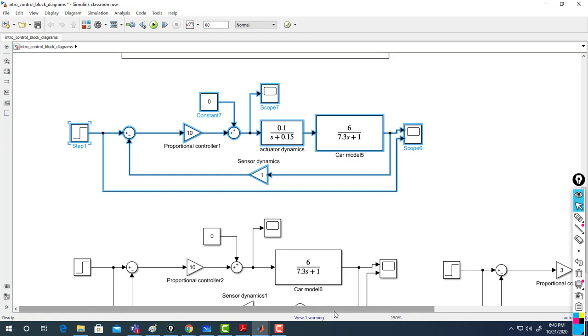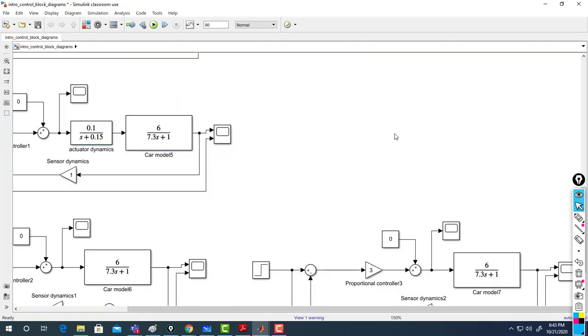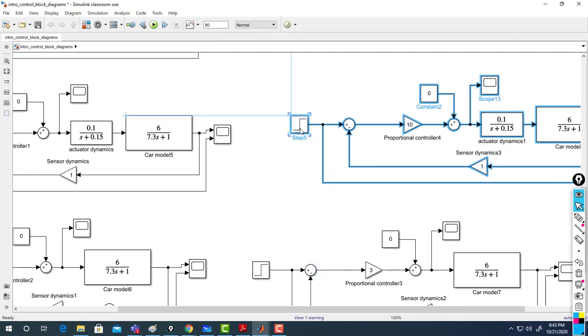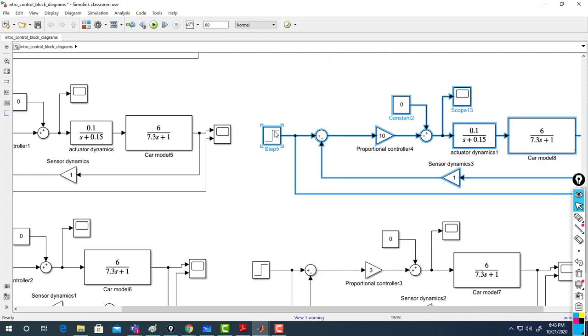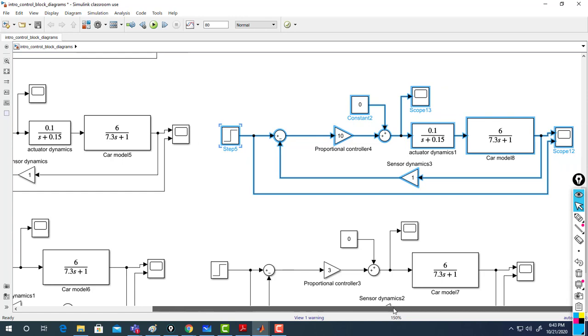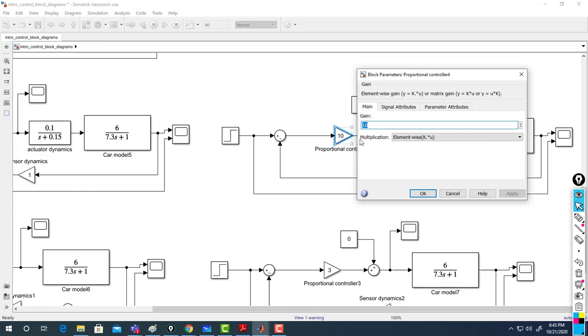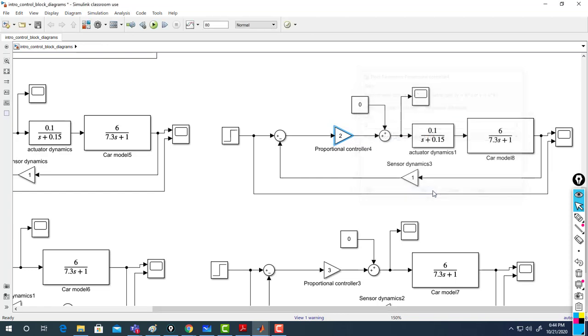Doctor, as a sum up, if we increase the DC gain we get more overshoot, and it makes the system faster, right? Yeah. Always. It becomes faster. The advantage is always there: the system is faster and has less steady state error. But you have an inconvenience, like you will increase the oscillation. That's one of them. It also amplifies noise and saturates your actuator.